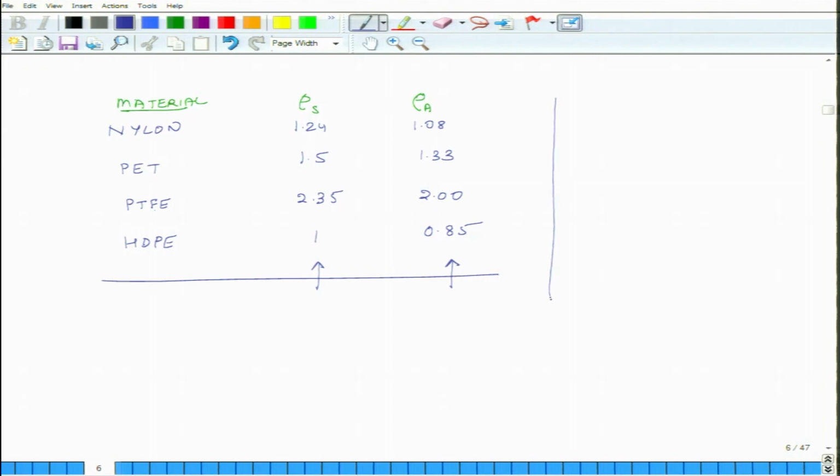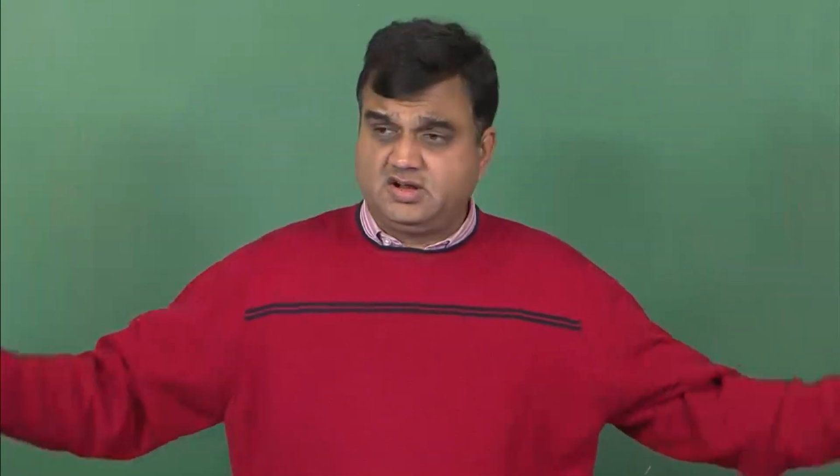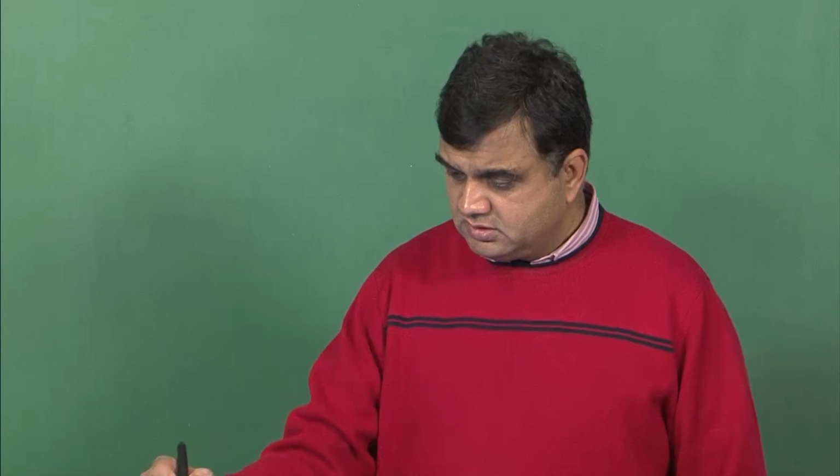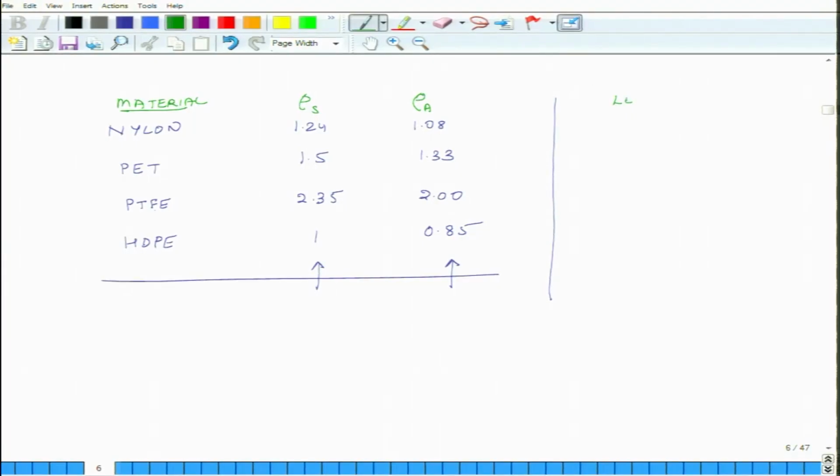And you will wonder what is the level of crystallinity in these things. So, if it is 100%, everything is very nicely organized, then it is 100% crystalline. But in general, let us look at some numbers. Crystallinity levels, level of crystallinity. So, let us look at polyethylene, and which polyethylene are we talking about? High density polyethylene. Okay. In high density polyethylene you can have something like 70 to 80% crystallinity.